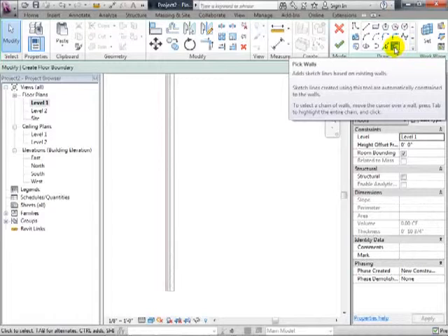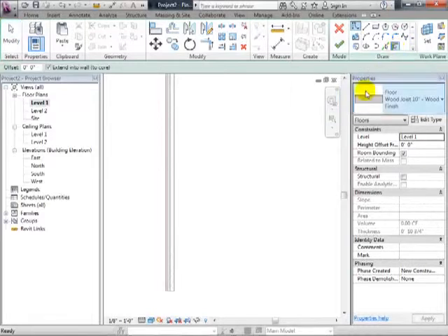And when we choose that tool, as opposed to just drawing the line at a specific location, we have this choice of whether or not to extend the floor into the wall core. Now, that's something generally you'd like to do, and let's talk about what the impact is. If you choose the floor to go all the way to the outside surface of the wall or the inside surface of the wall, there are some structural details where that works that way, where you actually have the full floor all the way out.